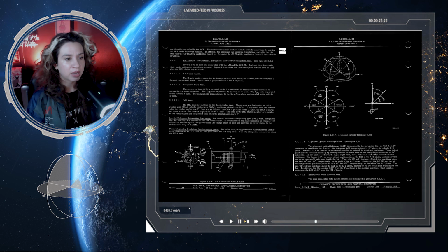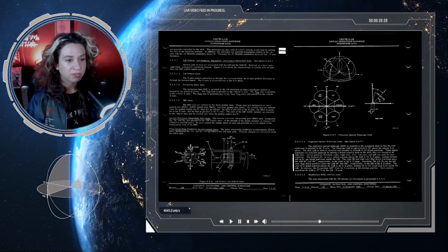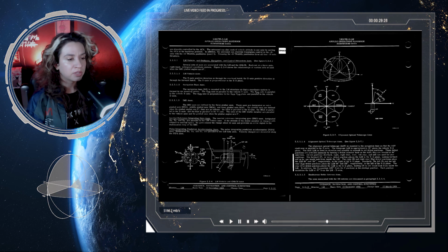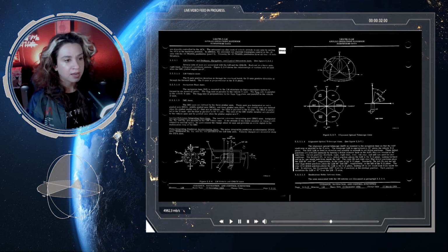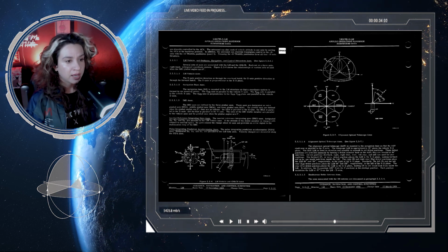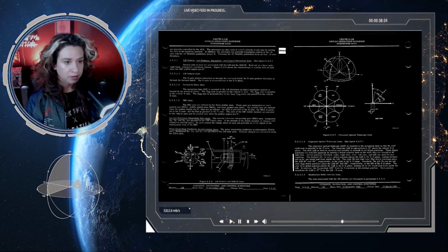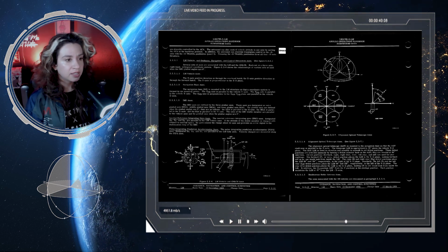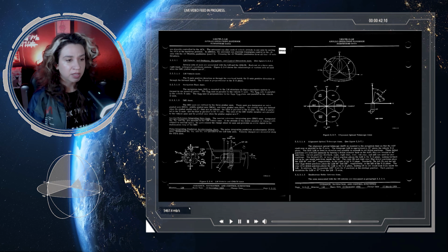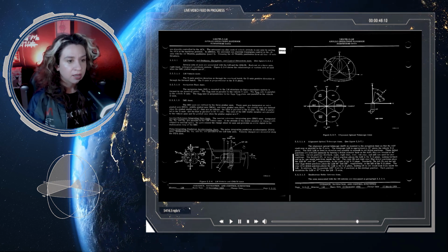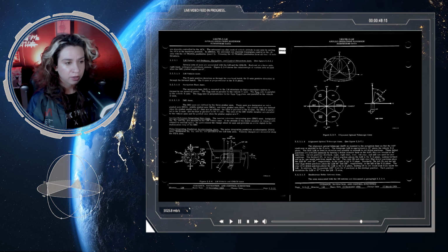The telescope LOS is approximately 45 degrees above the vehicle YZ plane. The AOT LOS is fixed in elevation and movable in azimuth to the 6 detent positions. These detent positions are selected manually by turning the detent selector knob on the AOT. They are located at 60-degree intervals.